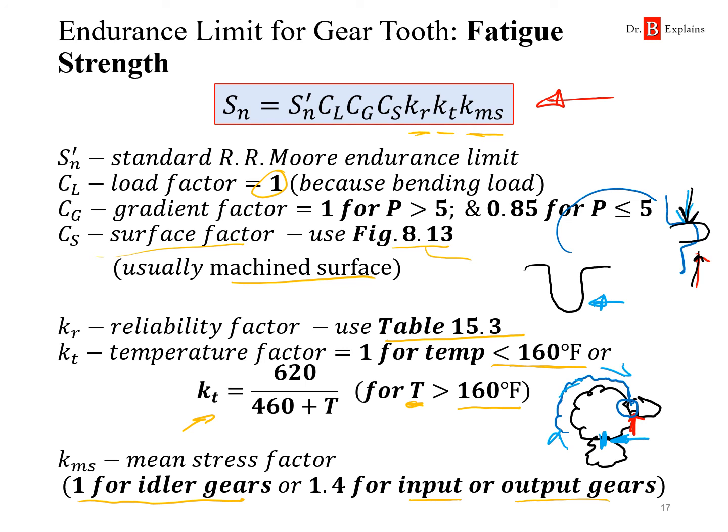If we just look at the gear tooth on the pinion, let me draw it over here. Let me say the pinion is green. Every time, the pinion is applying the load to the idler this way. So what is the pinion going to feel? It's going to feel the equal and opposite, but because there's nothing else, it's always going to feel the load in this direction, only one direction. So the mean stress, I'm jumping the gun here.